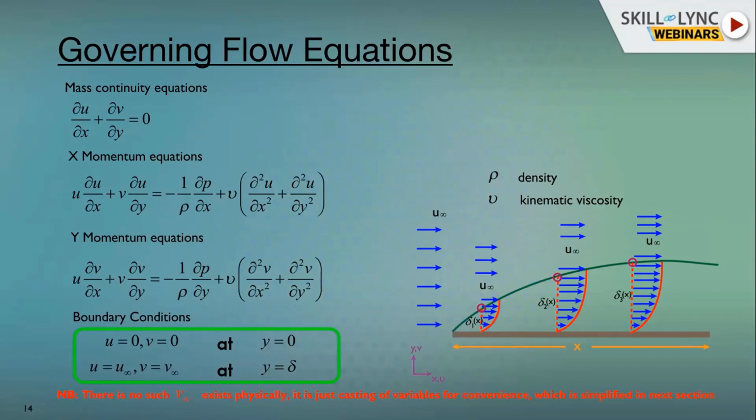Even earlier I have discussed this: viscosity is a messenger. This gives the message of the presence of the solid wall by the propagation of the viscosity, right? Even if there is a single fluid dynamics, you have two kinds of viscosity. Even if the physical phenomena remain unchanged, you have two notions of viscosity. One is dynamic viscosity mu, and one is the dynamic viscosity to density ratio that defines the kinematic viscosity nu. So what is the importance of having two viscosities, right?